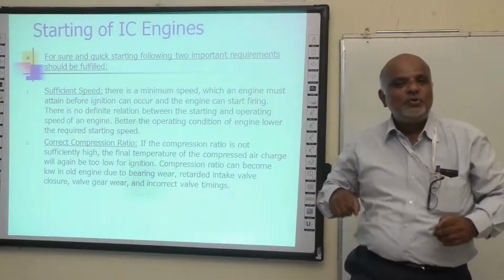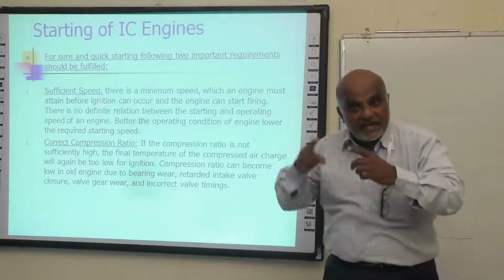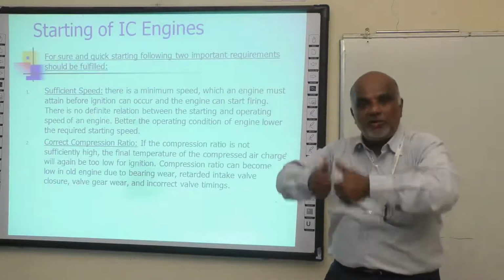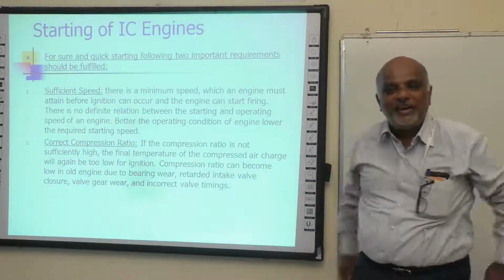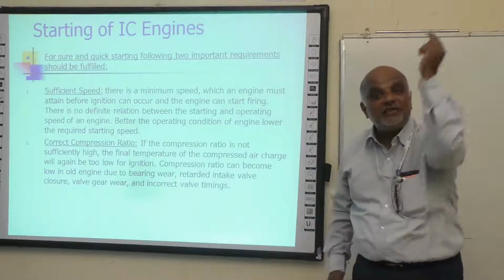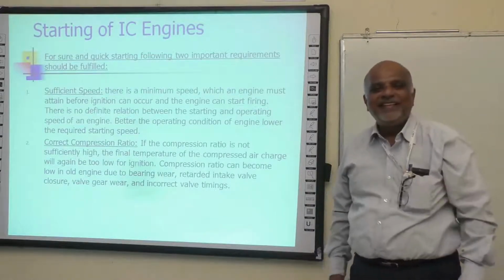What do you do when you take the starting pedal and give it 2 kicks? You're making the piston move up and down, compressing the air and making the air reach the spontaneous ignition temperature of the fuel. That's what you're doing.